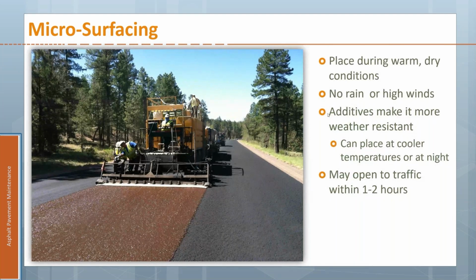The time to place this is very similar to slurry seal, warm, dry conditions. You don't want any rain or high winds. The additives in it, though, with that polymer modification, do make it a little bit more weather resistant. So it's more applicable if you wanted to do a project like this at night, in a little bit cooler temperatures.